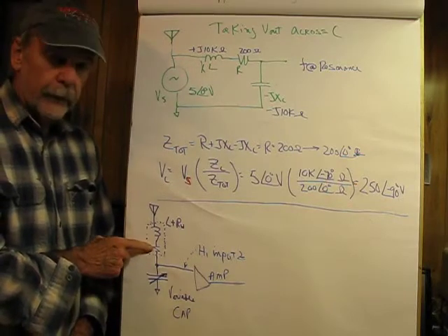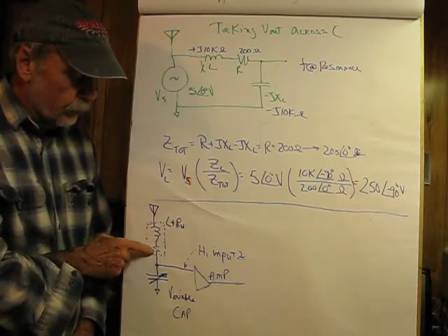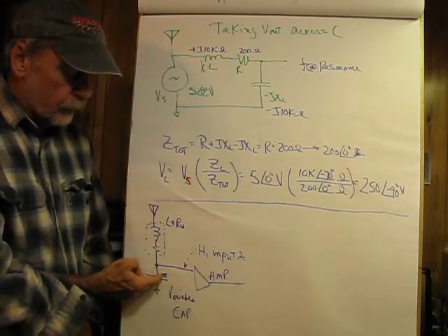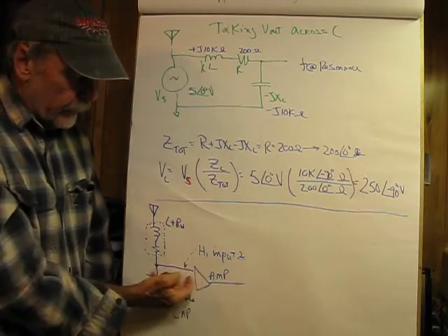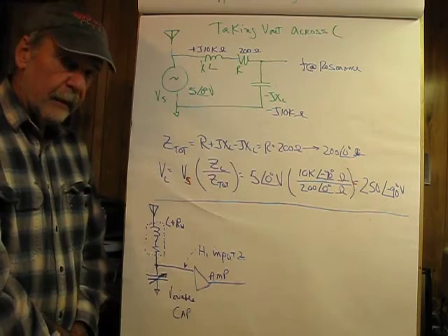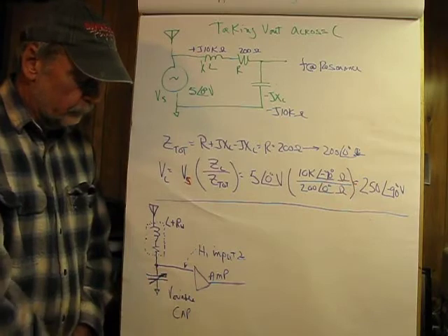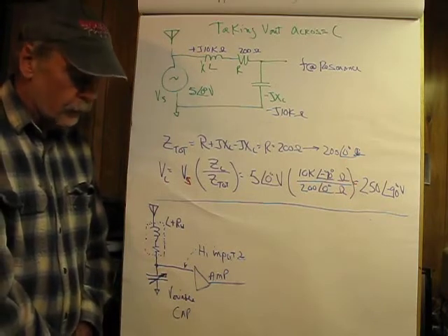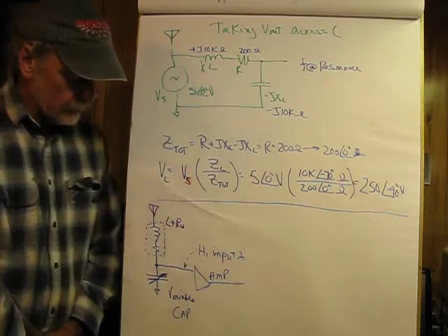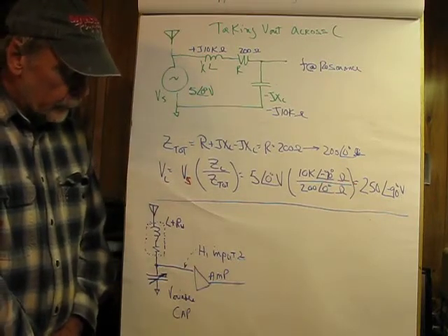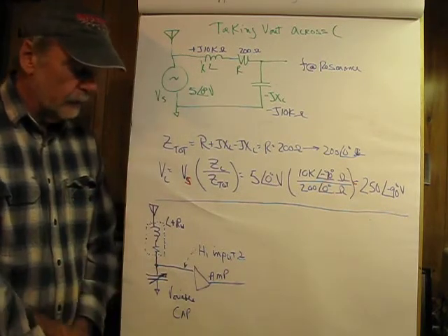Now I've included R in here, as a loss, as you know, as part of the resistance of the circuit. And I've made the capacitor variable so I can tune it. And the input of any amplifiers that follow would have to be very high impedance so as not to load X sub C here, because that throws a little variable in there which will reduce the gain. So we could actually use this circuit as a tuner and pick up some nice benefits from the Q rise in voltage across the reactive elements.